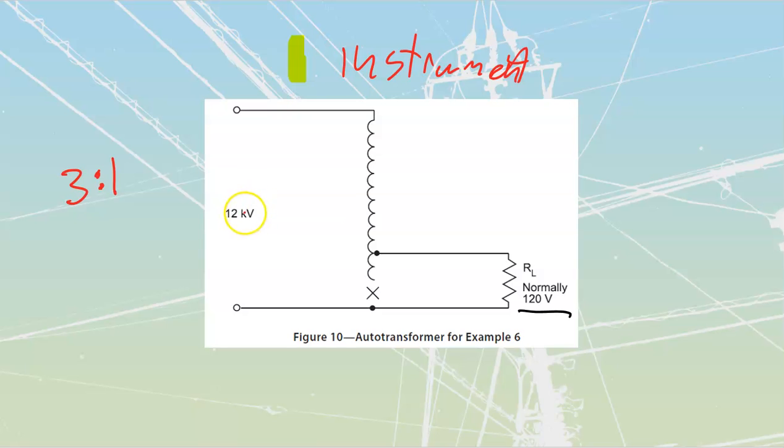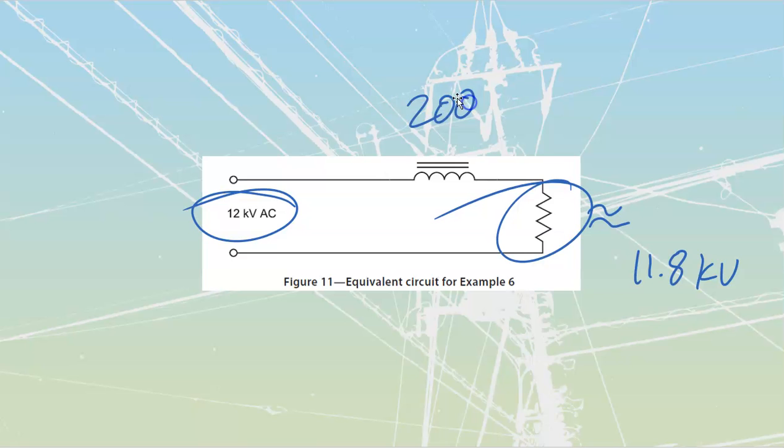If my high side was 347 volts with a low side of 120 volts, that's a little bit underneath a 3-to-1 ratio. If I have a good operating transformer, perfect, that's going to be fine. If I were to have that open over there, at that point I'm going to be somewhat close to where I need to be.